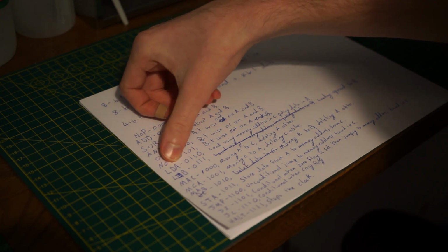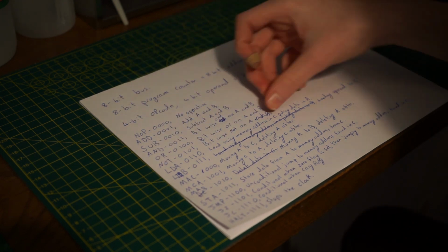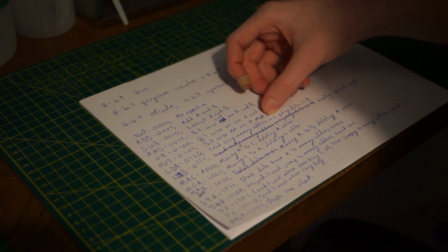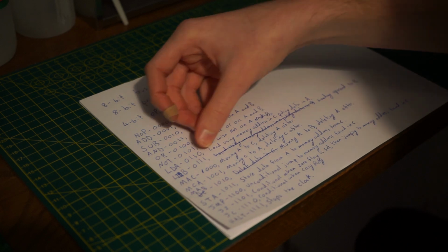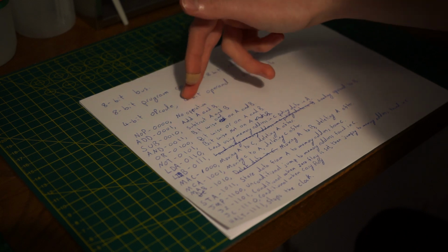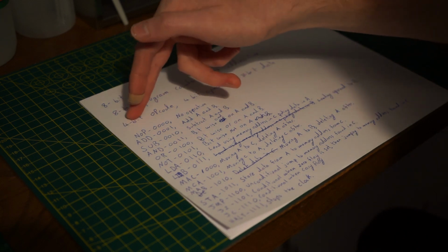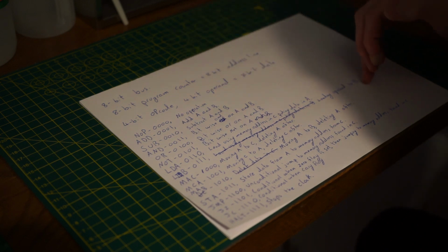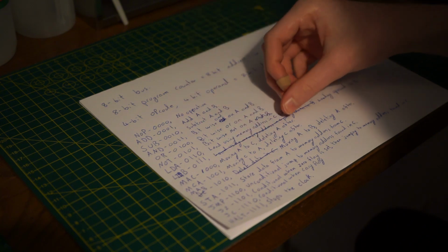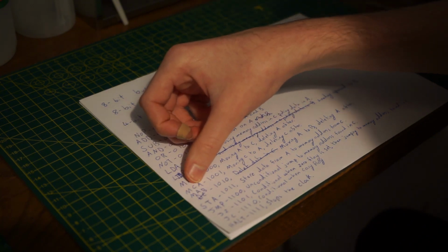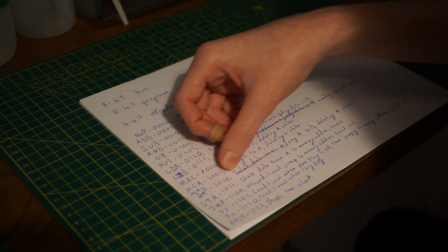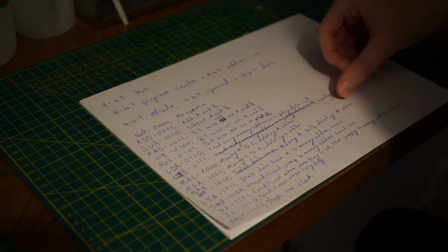We have a load A, so we load using the memory address in C. Our C register will always contain the address that we're loading from, storing to, or jumping to, should I say. Then we have our load immediate B, so we load the operand, the 4 bits in the instruction, but not the opcode, just the operand, and that gets put into B. MAC, we move A to C, deleting what's in A afterwards, and MCA is moving C to A, but we delete C after. And MAB, we're moving A to B, deleting A after.